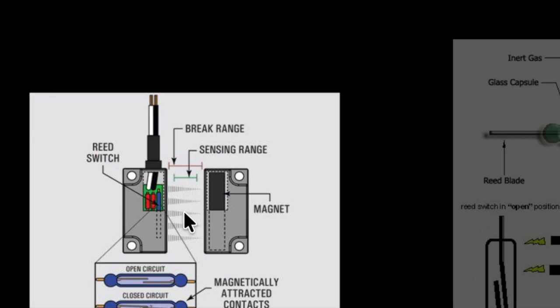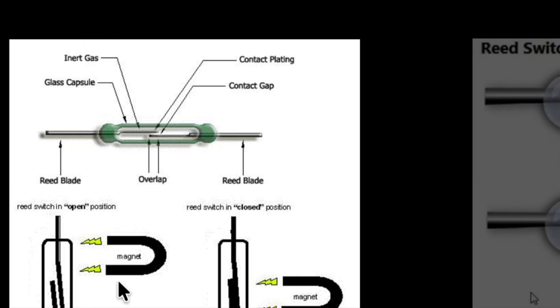The break range is where your circuit is going to be open, and this is the influence range of the sensing area. If you come into the nearby range, it is going to turn on the LED of the magnetic reed switch, so it starts working. Then you have two types of workflow, normal open and normal close. This is the basic diagram.